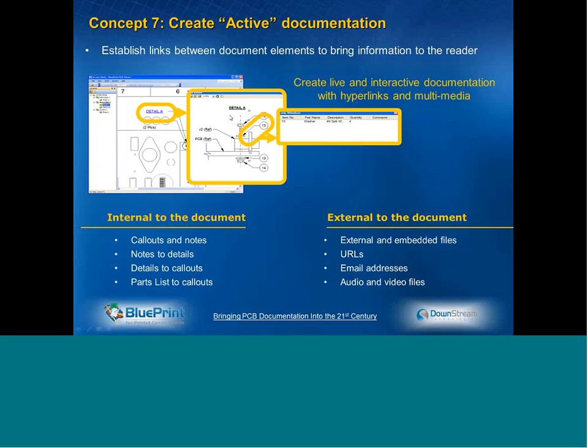Now that could be 3 sheets further into the drawing set, but it will bring up a picture of Detail A. And inside of Detail A is showing an assembly here, and one of the items in assembly is number 13. If I click on 13, it actually goes out to the parts list and shows me that item in the parts list. So you can have these intelligent links between the various items in your drawings.